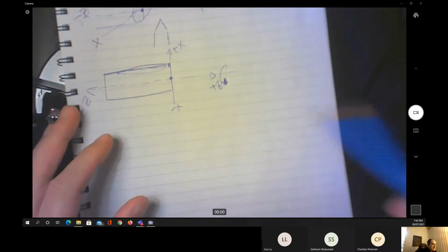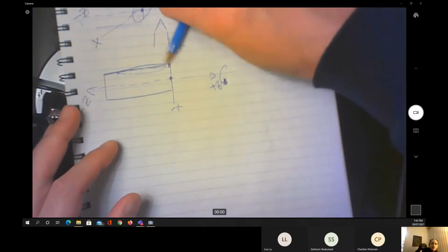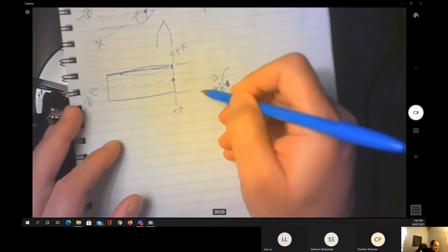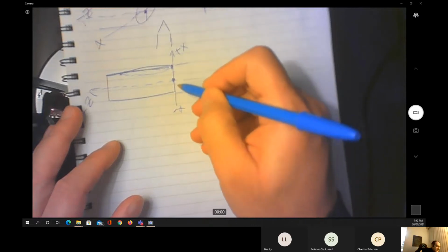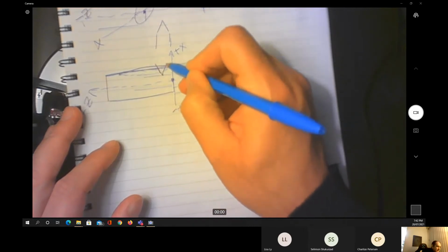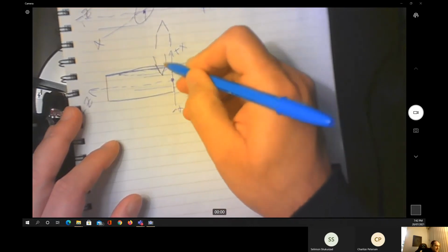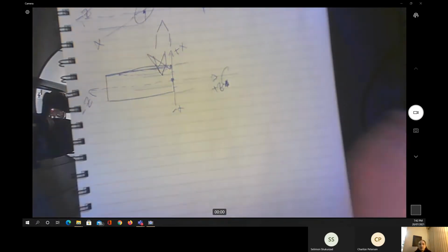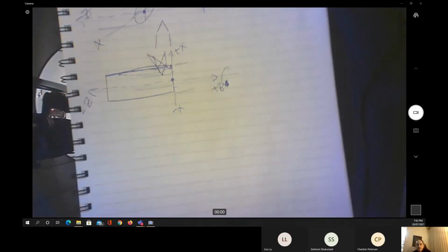Now, the problem is, in the case of the turning, if I would like to take the diameter from this amount to that amount, I cannot insert my cutting tool directly to this position. That's wrong, because this will damage your cutting tool instantaneously.